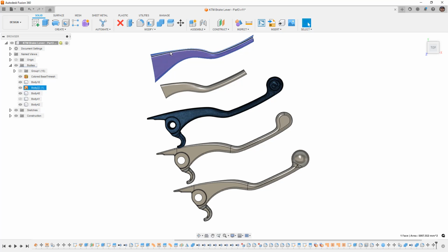So if you're going to go that route for something like this lever, you would want to make sure that you build the surface and freeform out far enough that you can add those prismatic features manually and you can have the underlying surface there.